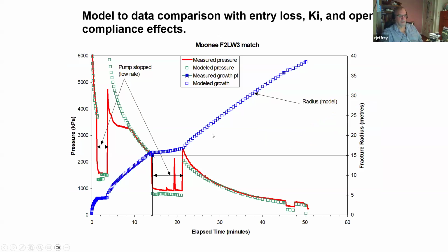So we did build a model with Tony Satari that accounted for the free surface near the fracture growth. And we were able to calibrate that model with direct measurements of fracture growth with offset monitoring holes installed into the roof, with instrumentation then trailed through the supports also and connected to logging devices.